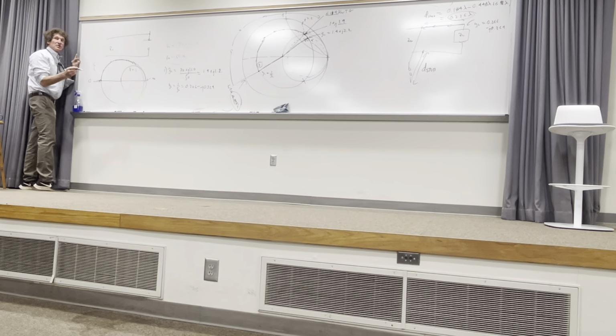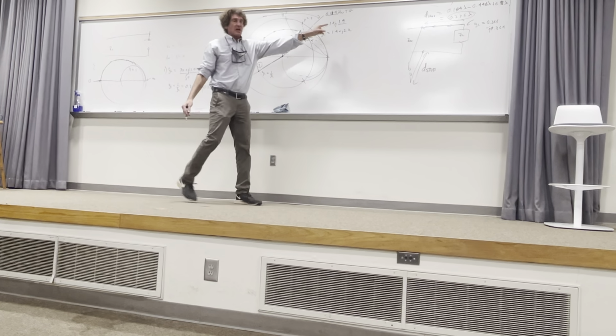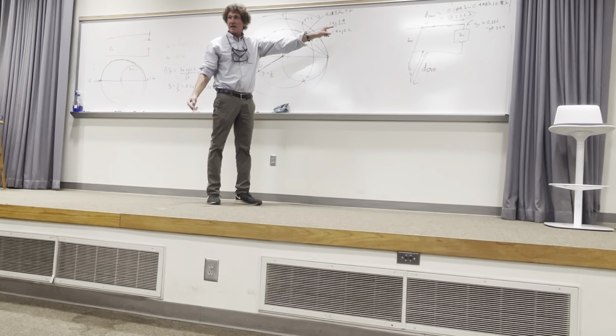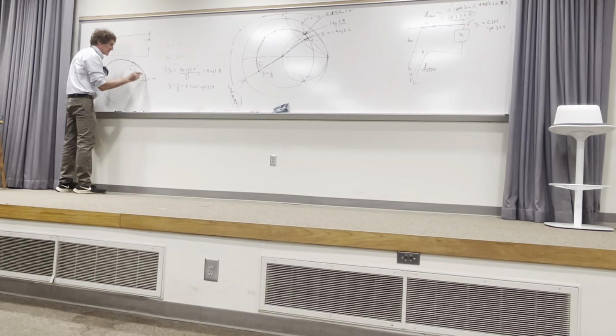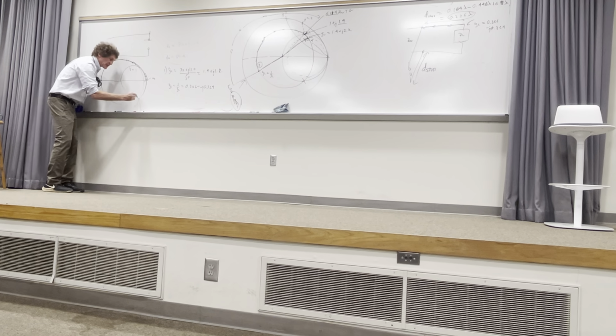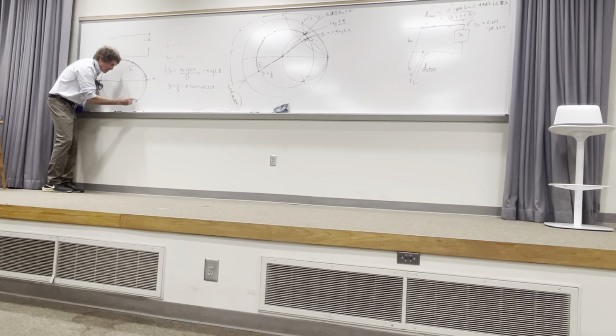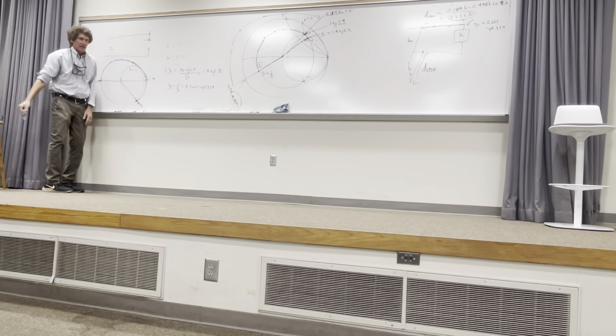How far do I have to move, class? Until J is, now think, this is positive J 1.9. What do we want to land on? Minus J 1.9. Where is that? Well, it's at least a quarter wavelength, right? Until we get a quarter wavelength around, we're not getting negative values of J, right? Everybody? Now you're going to keep going until you hit, I'm going to guess it's about here, and you're going to see it'll be J 1.9, and it's got a minus there, but I don't think it's indicated in all Smith charts. So then shoot a line through there.